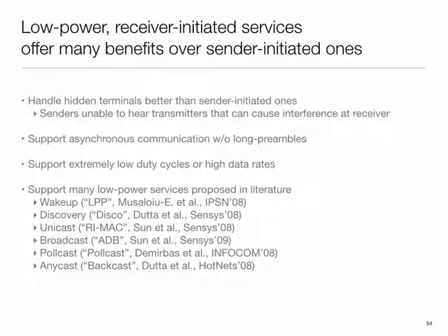Remember with the sender initiated approach, with this rare event scenario, the sender started sending and sent a long preamble in the hope that the receiver was guaranteed to wake up. By doing it receiver initiated, we eliminate that. So when the rare event happens, we do nothing. But the receiver, at the next time it wakes up, is going to check with us: do you have something to send? So it's going to send out the probe. So we eliminate the long preamble, and we can therefore support even lower duty cycle than otherwise. So that's the basic concept.